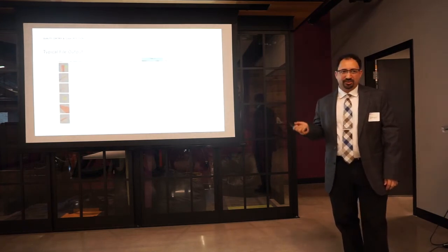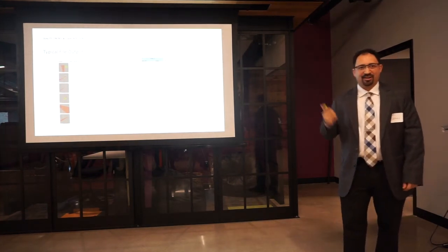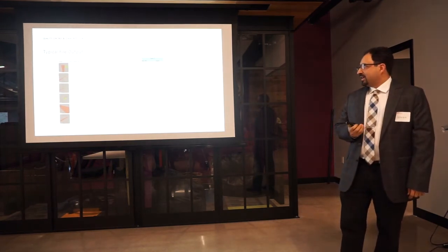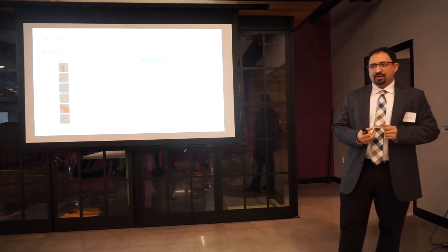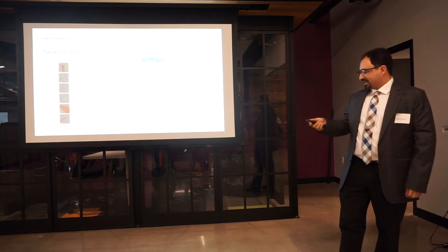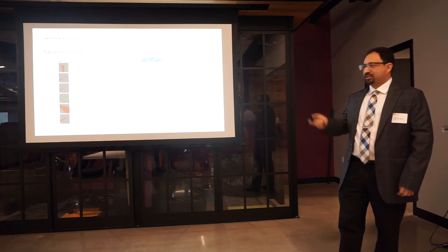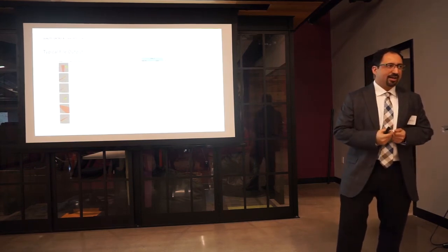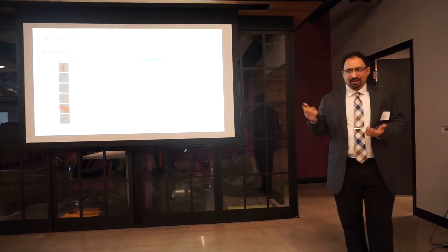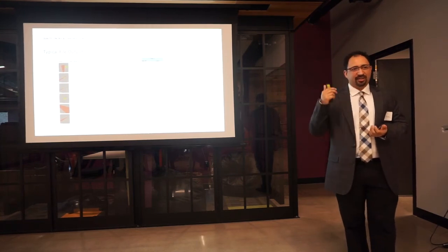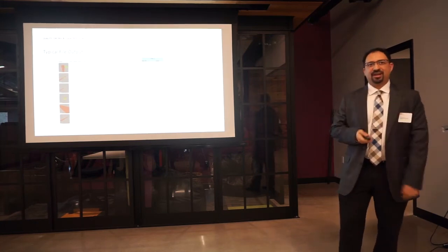This was our mechanical versus structural. This is just 6 clashes of I think about 50 or so that this report had generated. And we provide this, the red and green items. The structural was the red and the green would be the mechanical. It gives you the exact location, the clash point rather, the element ID, which you can type into your file and find the exact object that's interfering and resolve the clash. I mean, you put a duct through a corridor, right there you might create 30 clashes just because of the structure. So a lot of the clashes that we generate are resolved with a simple drop of an item.